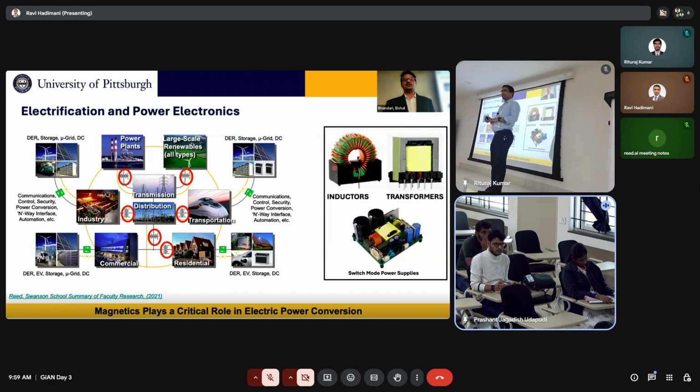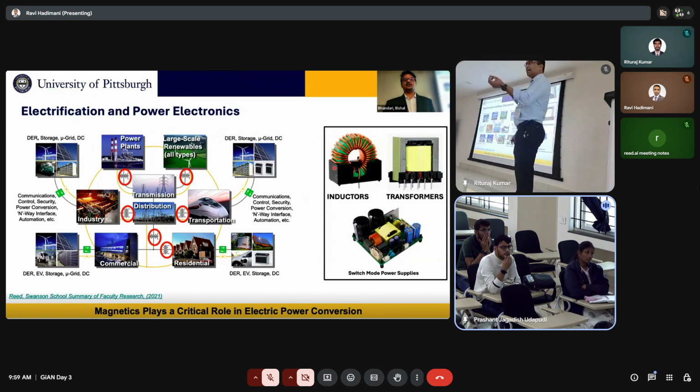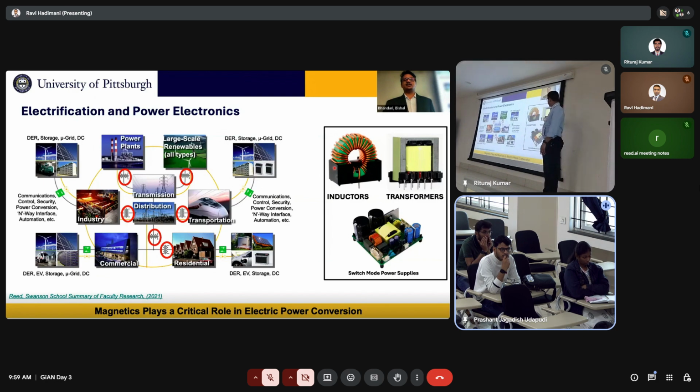How the magnetic materials are used in motors, generators, transformers, or inductors. We did not talk much about inductors, but that's okay, because inductor needs the concept of induction, which is a big thing in circuits. Whereas transformers, you understand, right? Voltage has to go up when it needs to be transmitted. So you need electrical steel here. These are laminates of electrical steel. You can't just have a big core of electrical steel. They have to make thin slices of electrical steel so that there are no eddy currents.